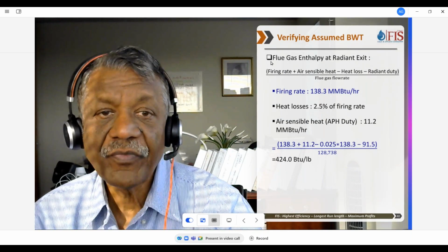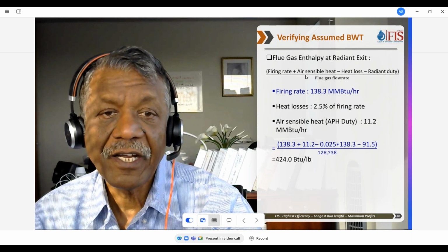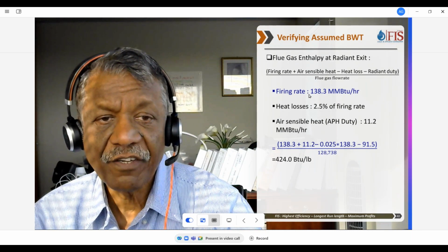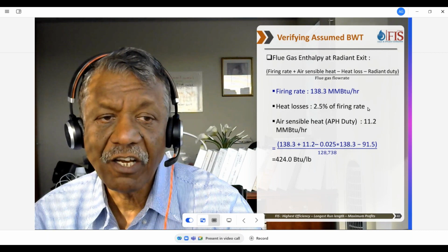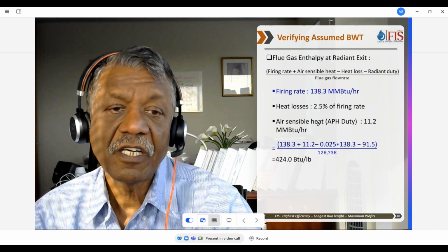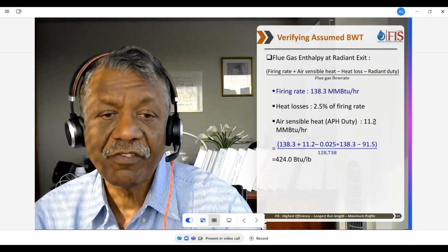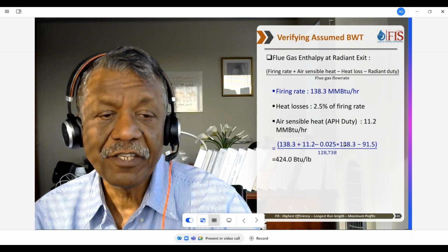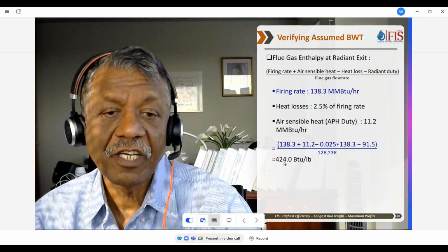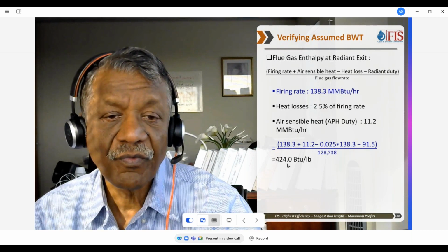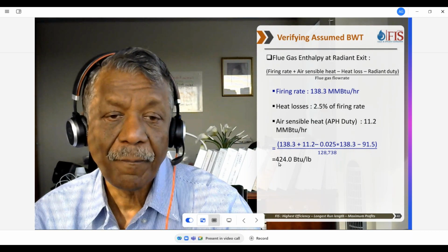So here we are doing the flue gas enthalpy at the radiant section. We get a firing rate, we calculate the heat losses, and we add how much air preheater duty we are recovering. By doing this, we get a flue gas enthalpy of 424 BTU per pound.